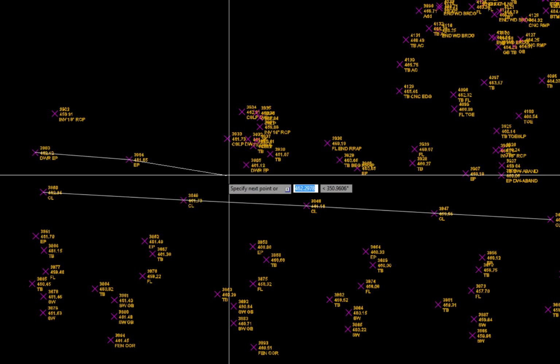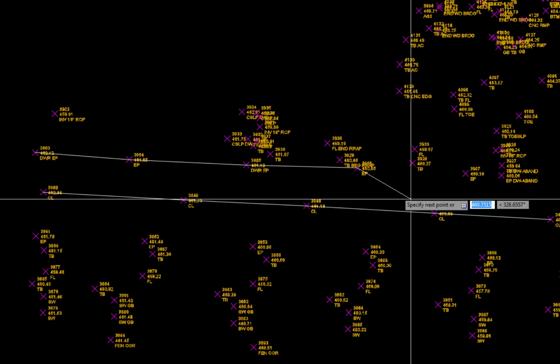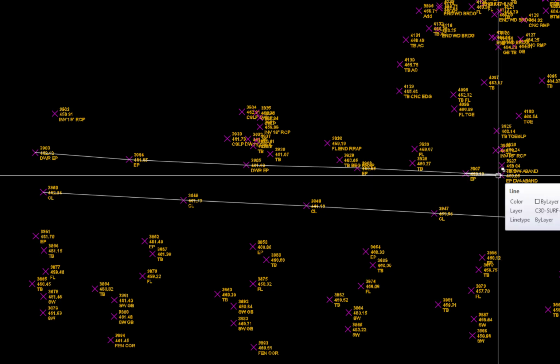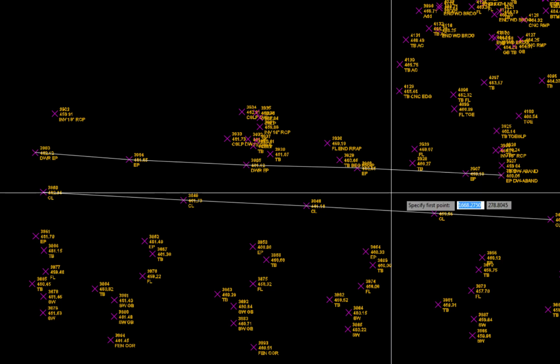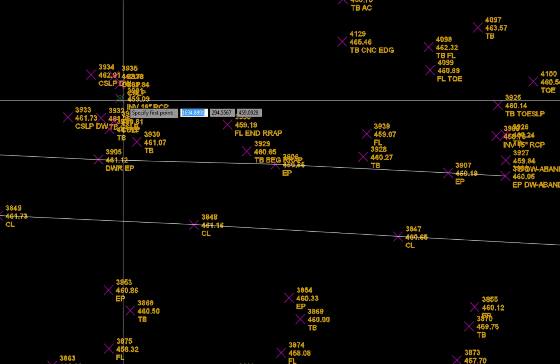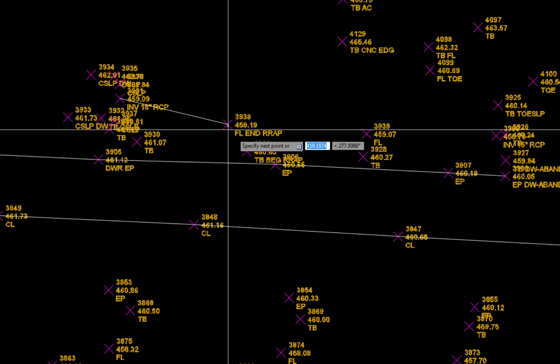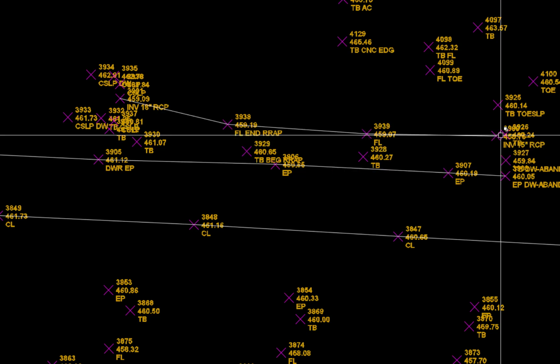Draw a line along the edge of pavement. Again, depress enter to stop the line. Depress enter again to start a new line. Draw a line along the existing ditch flow line. Continue the process to draw lines along the crests and sags in the drawing.